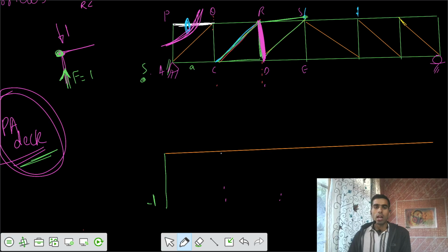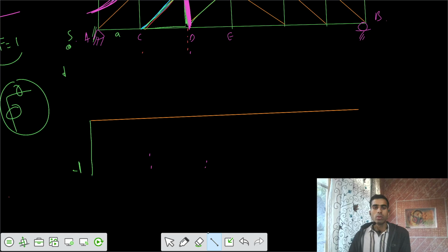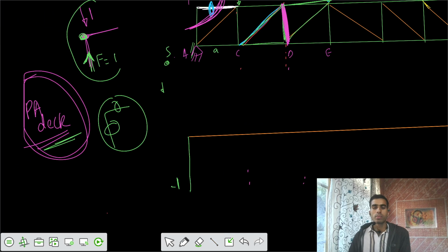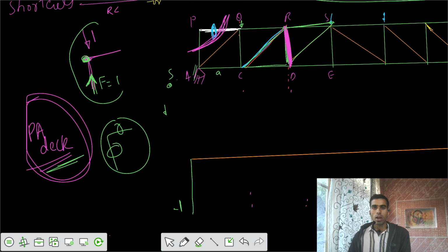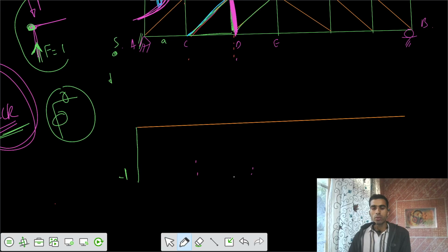But if the load is at Q, can you tell me what is the force? Because then, I would say if this is your section, load is somewhere here, and on this joint there is no load. I would say this is also 0, this is also 0. So on all points you have ILD of 0. So then, how can you finally join it? If all points are 0 and you have ordinate here 1, then where is the possibility you can join it?